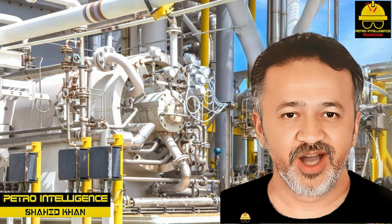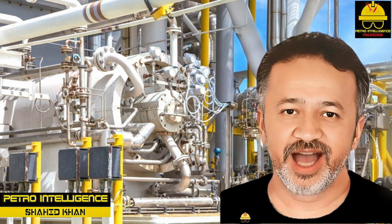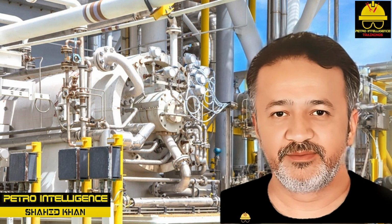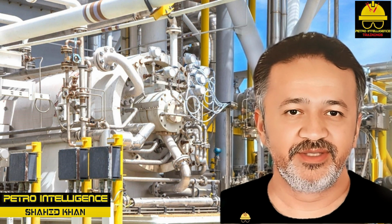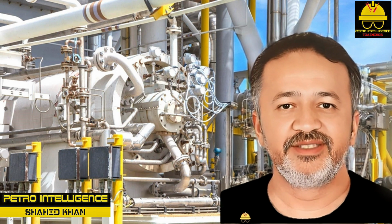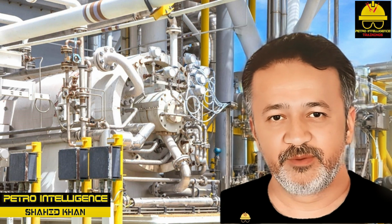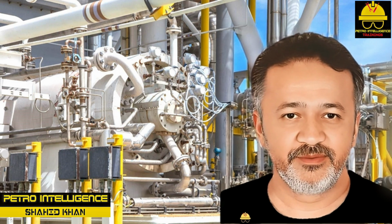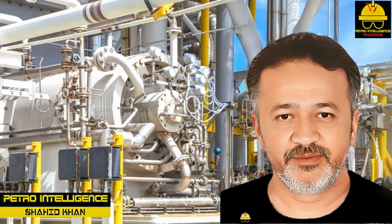Gases and vapors are compressible. Compression decreases volume by moving gas molecules close together. Compressed gases will resume their original shape when released. Compressed gases produce heat because of molecular friction. The higher the pressure, the smaller the volume. Gas volume varies with temperature and pressure.